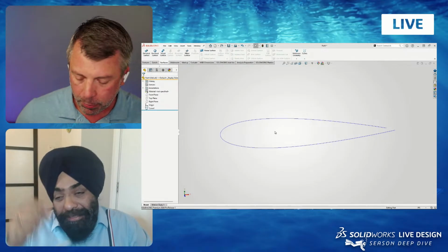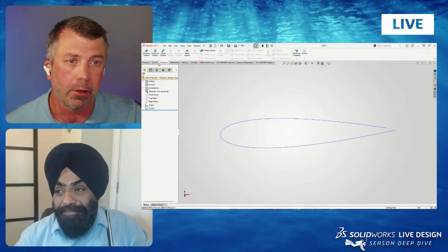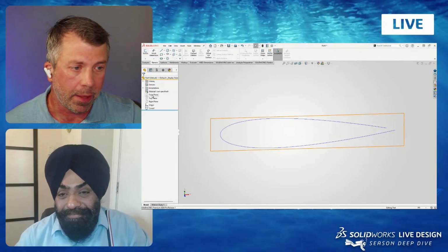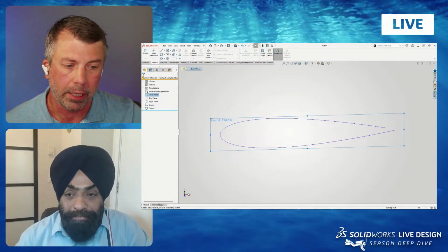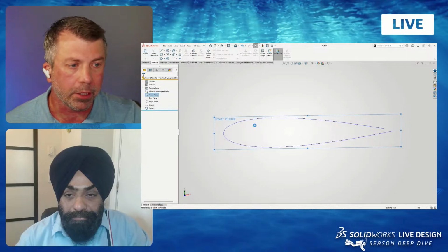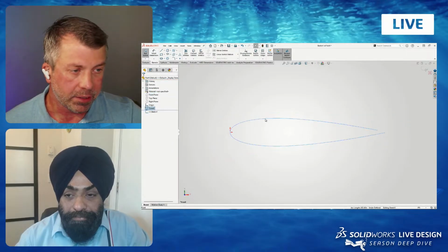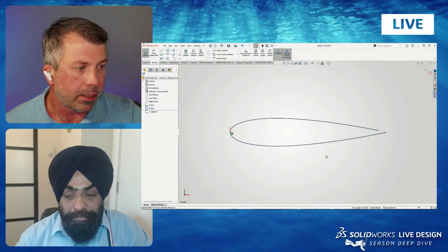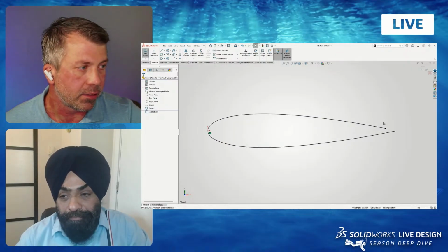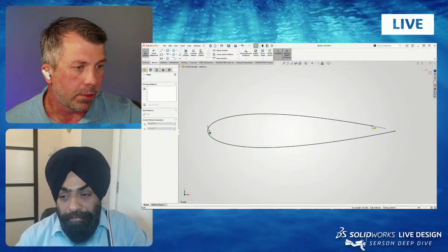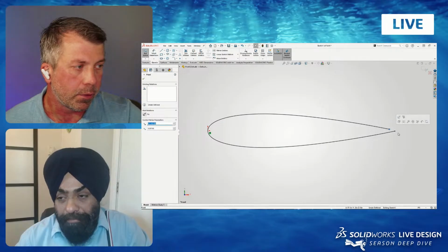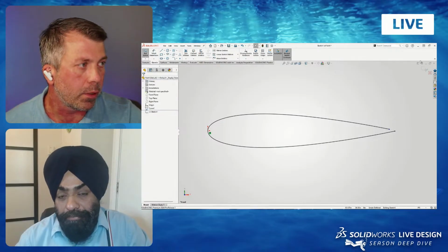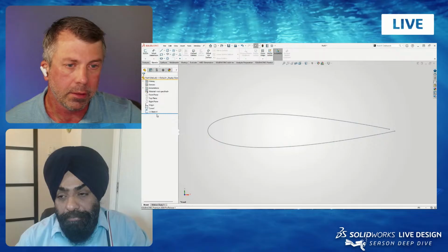Now, you can do it a couple ways. My instinct was the same thing, right? I'm going to come in and create a sketch on that same plane because we used X and Y coordinates. We're on the front plane, which is X and Y. I'm going to create a sketch, and we can select it and simply do Convert Entities, and that's going to give us that conversion. You'll notice that it's a little funky at first, but we can actually start to drag these endpoints out if we wanted to complete this. That's one way to do it. That's actually the way I'm going to do it.